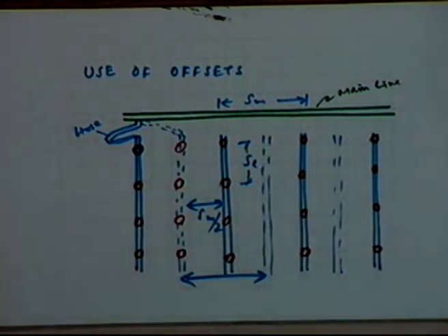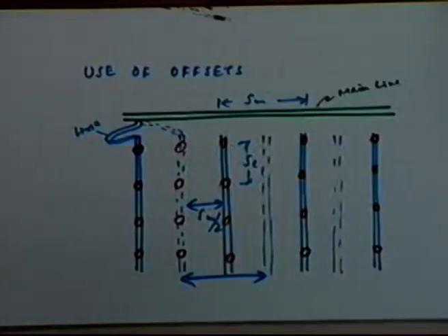Okay. Yes, please. Can we do the same thing with the nozzle location if we shift just by half nozzle location? I mean, we move this lateral by SL by 2 in the new location. In which direction? In the same direction in which the laterals are placed. If we shift the lateral by SL by 2 distance, then the nozzle will be in the new position, and the distribution which we are getting in this diagram will get just the perpendicular shift.